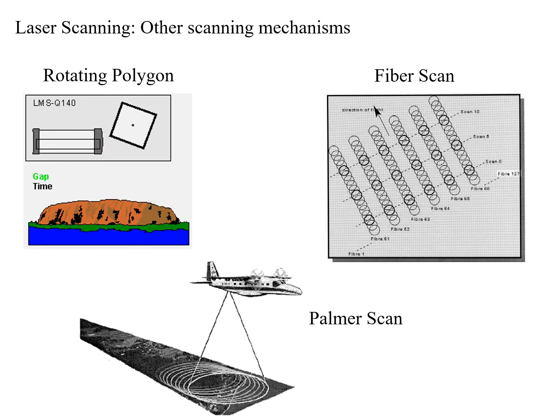The interesting thing about the Palmer scanner is you look forward and you look backward at the things you're flying over, and so you have a chance to get two observations. And if you're doing work on ice sheets and you have crevasses that you really need to get into in order to understand the topography, this gives you two chances to get in the crevasse, depending on where the plane is and whether the scanner is looking forward or back at that time.